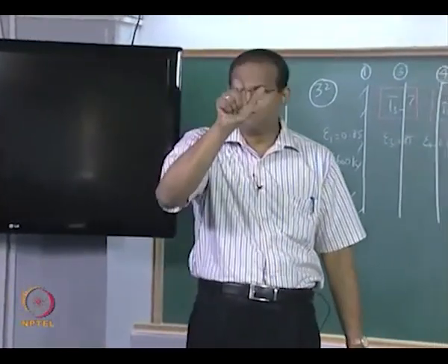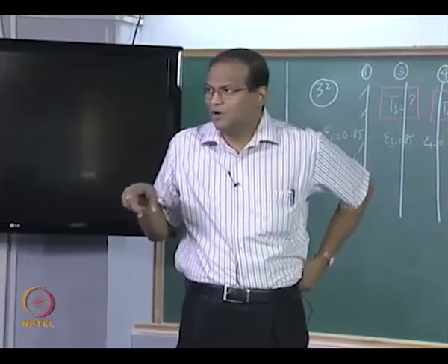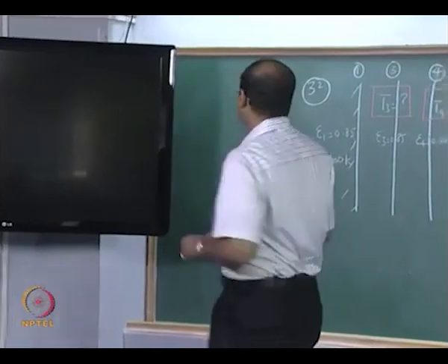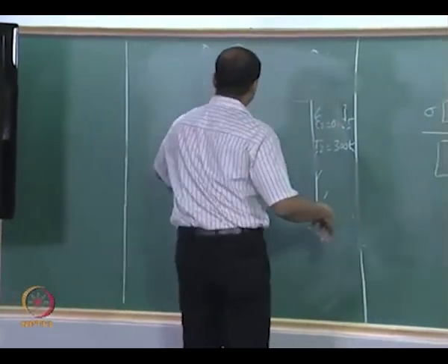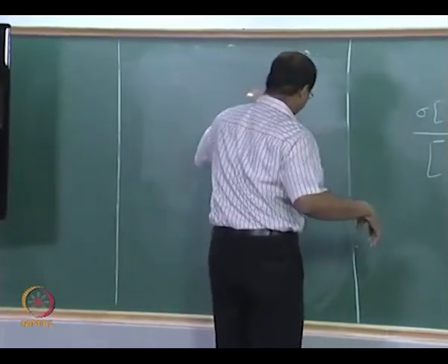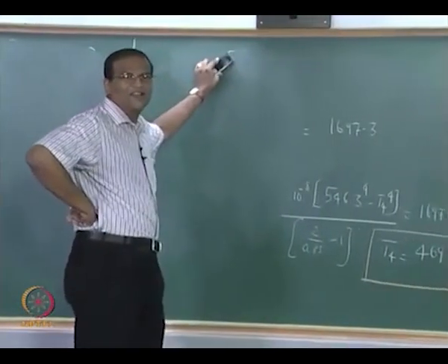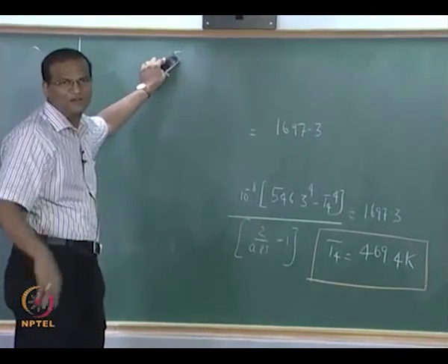If you consider them as one body, they have only one temperature. Because they are a re-radiating surface, the temperature or radiosity must be independent of their emissivity. That is what we derived in yesterday's class.